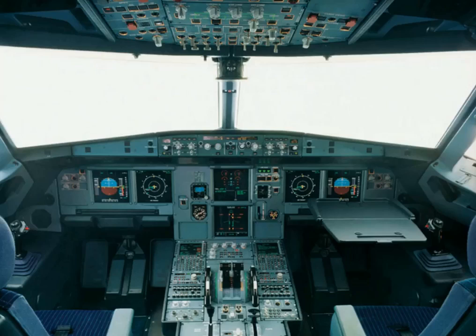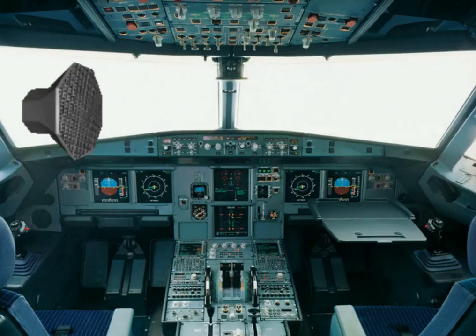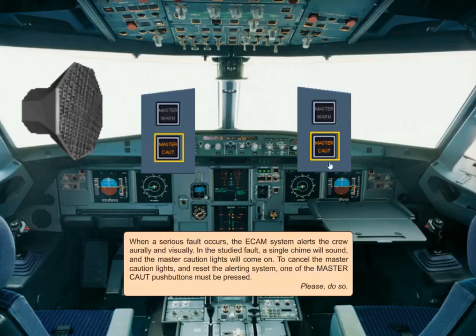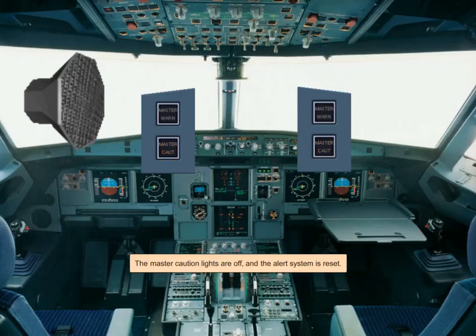When a serious fault occurs, the Ecam system alerts the crew, orally and visually. In the studied fault, a single chime will sound, and the master caution lights will come on. To cancel the master caution lights and reset the alerting system, one of the master caution push buttons must be pressed. Please do so. The master caution lights are off and the alert system is reset.